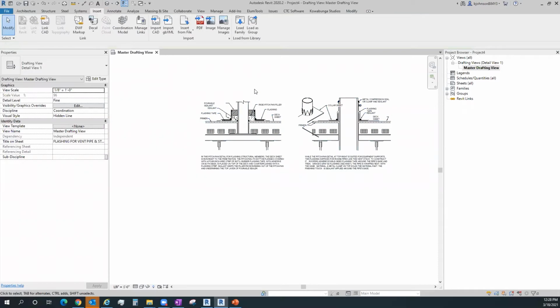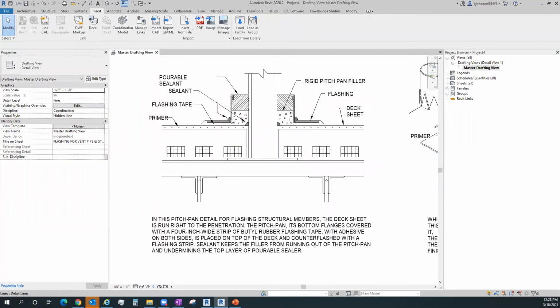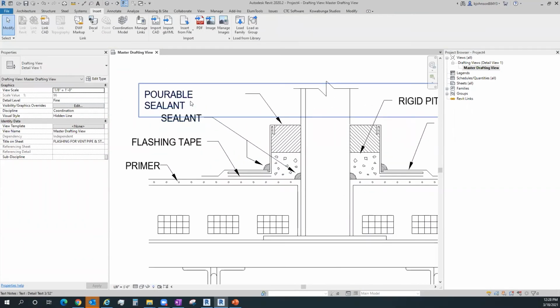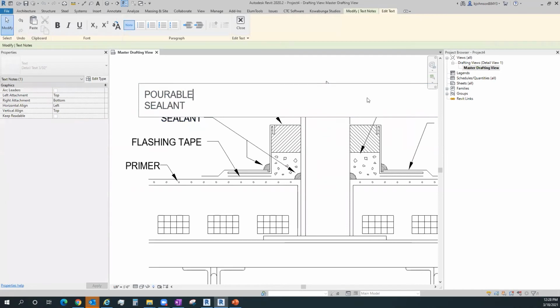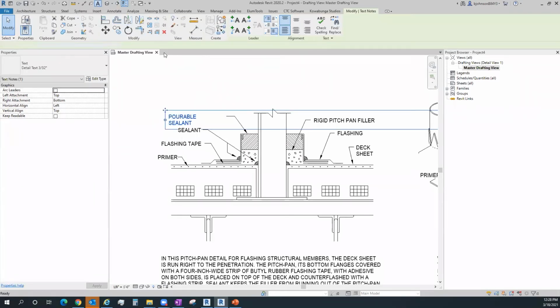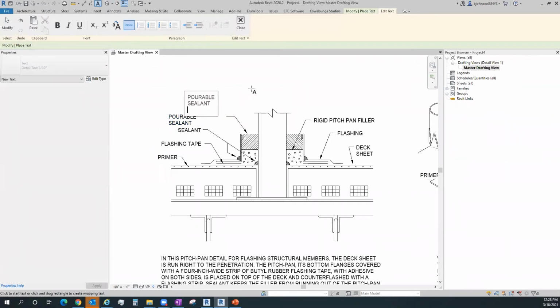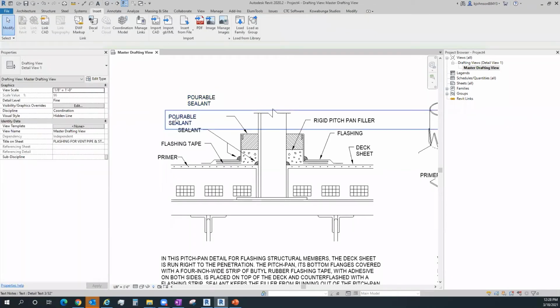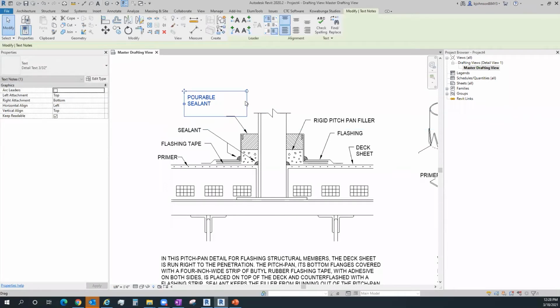And then the majority of my detail is completely converted. I still have things to do with my text. So in here, again, there's this really long one because I didn't explode my mtext. If I do a Control-C here on that, maybe I'll just stick a brand new text entity up here. And now it's a piece of Revit text. I can get rid of that long thing that I don't like. It's another way to get rid of that.